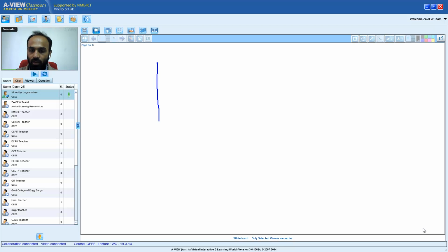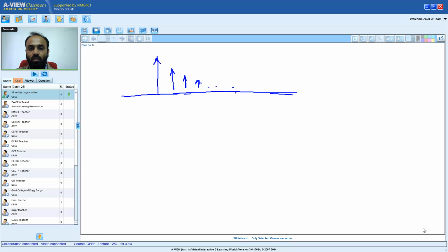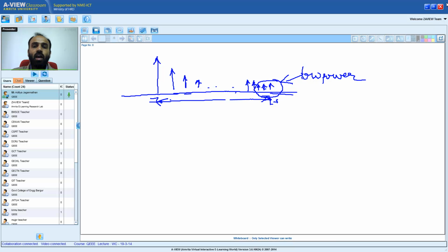Let us say I have a multipath delay profile which looks as follows. Let's say I have a large number of paths, but the multipath power profile is decaying. After some time I have many paths with very small power. Now if I simply say that the delay spread corresponds to this, it might not be a significant measure, right? Because several paths corresponding to this have very low power.